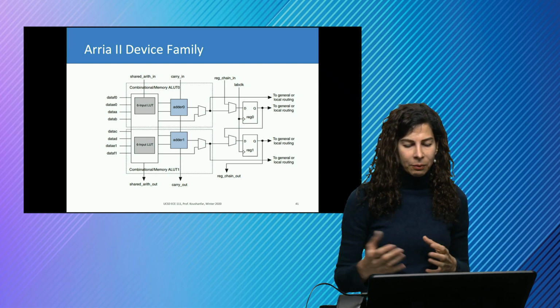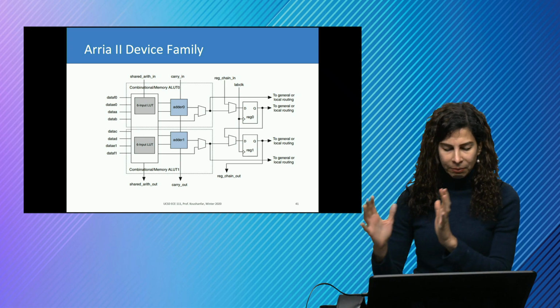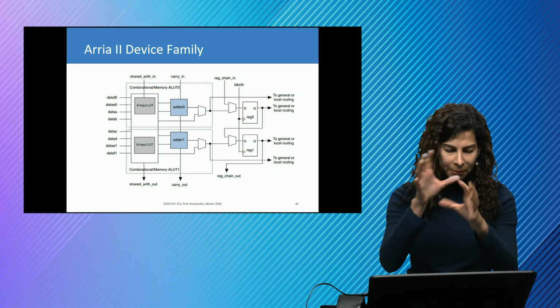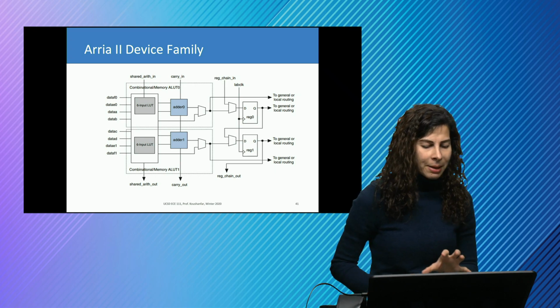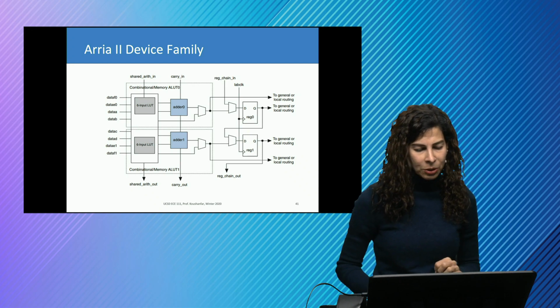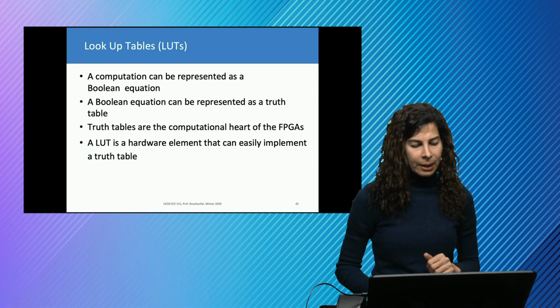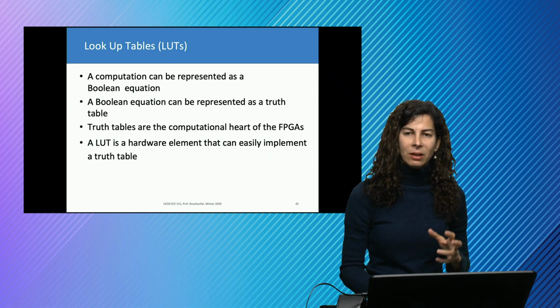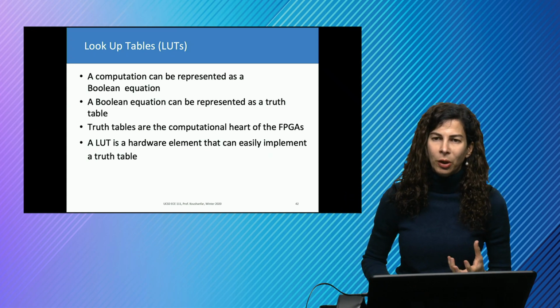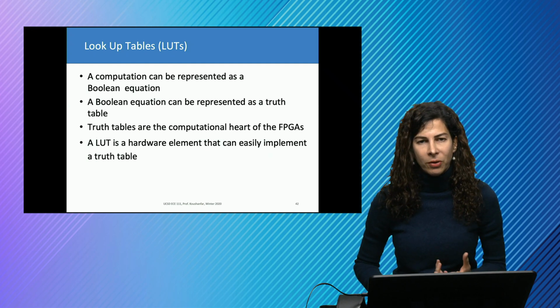And then we also have the logic that connects this combinational part, which we make in the LUTs, to a sequential register part. This can help us make combinational and sequential logic, as we will be seeing further.